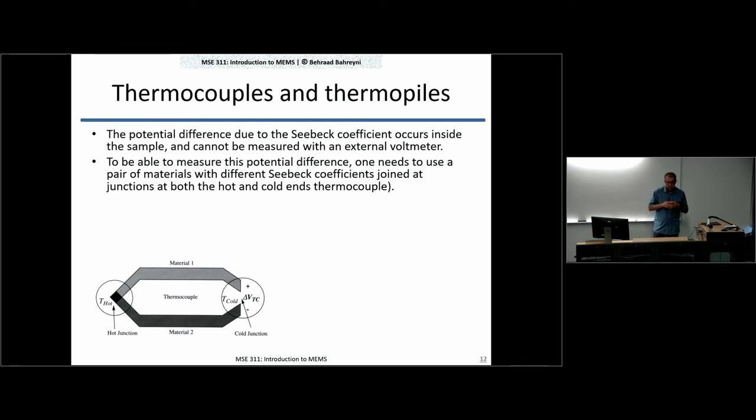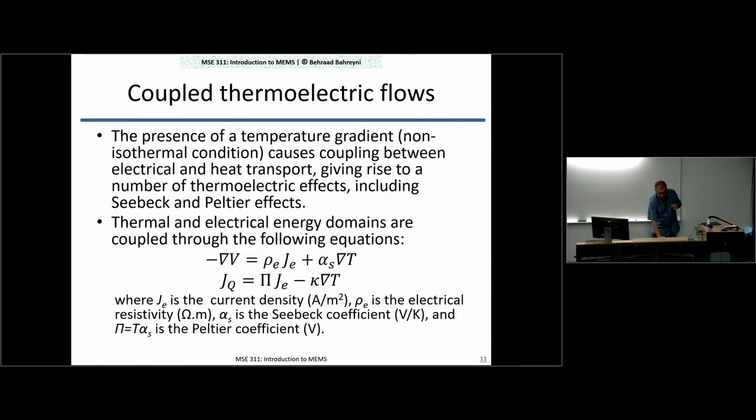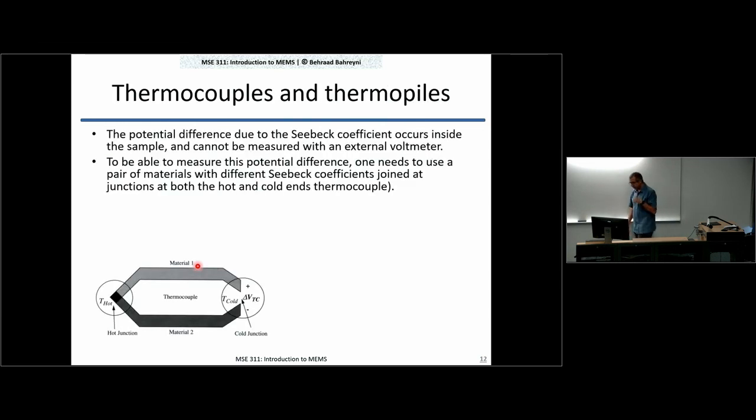But, yeah, for these thermocouples, you remember that in your equation you had a dependence on current as well as the temperature difference. In thermocouples, we measure that voltage with a very good voltmeter so that there is no current drawn. So this part is 0, and the voltage difference is entirely proportional to the temperature difference. But the voltages are nonetheless very small. You're talking about microvolts or tens of microvolts. So what we do here is that we put a bunch of these fellows in parallel.